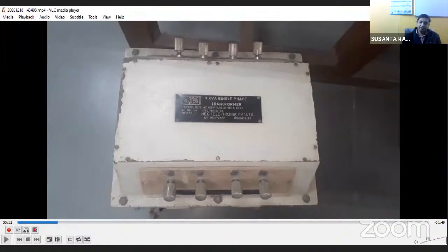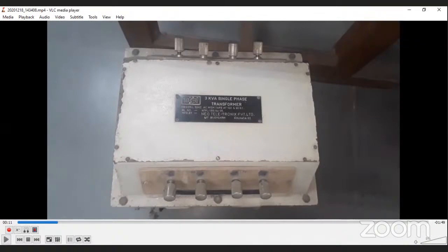If the multimeter shows full deflection, then there is connectivity, so it is continuous. Suppose from the left, if we go for 2 consecutive terminals and it shows continuity, what does it say? It says that the same coil exists between these 2 terminals.